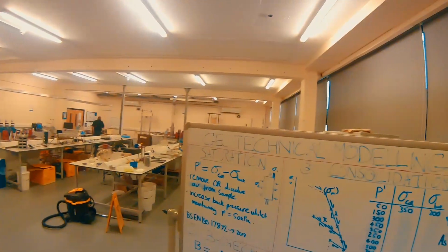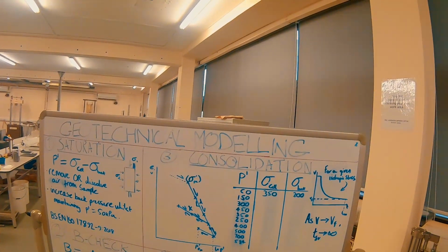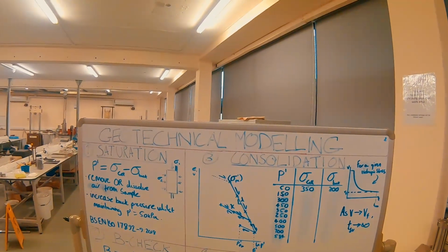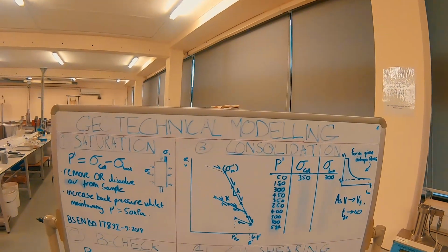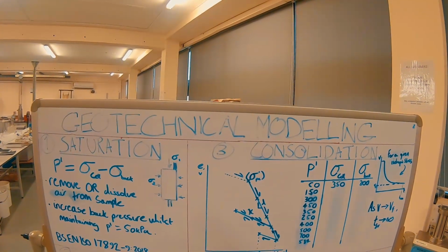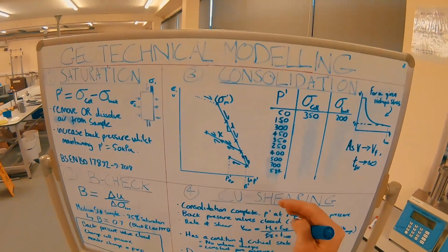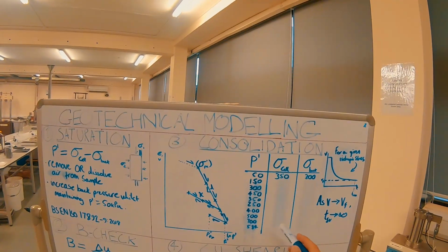Although we can estimate our pre-consolidation stress of around 50 kilopascals that we're at already, we do want to move fairly quickly past this point. So I'm going to assume, for the sake of argument, that once we get past 150, we know for sure that we are on our lambda line. So that's going to be the first point that we move to in our P dash.